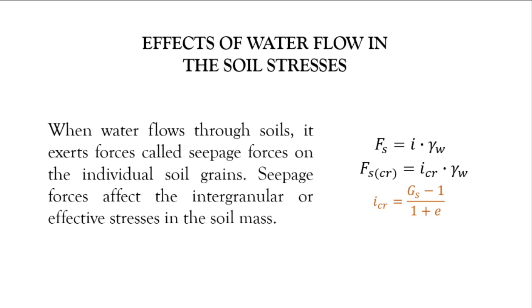Familiar naman tayo sa hydraulic gradient, that is delta H, or the change in water level at two different points divided by the distance between the two points. So if you want to solve the critical seepage force, just use the critical hydraulic gradient times the unit weight of water.